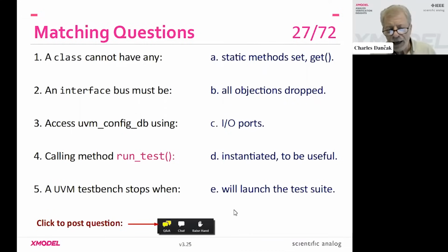I think I've mentioned at several points during the talk that many of these classes and objects are highly reusable, and only the driver and monitor have intimate knowledge of the details of the DUT, pinout, and timing. So it is highly reusable, and there's a lot of very sophisticated machinery like the phasing system that the user can just employ without even really knowing how it all works in detail.